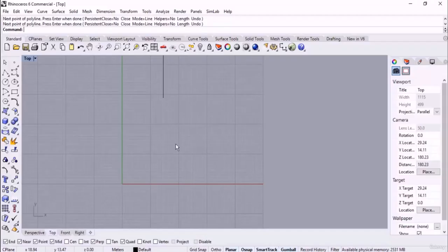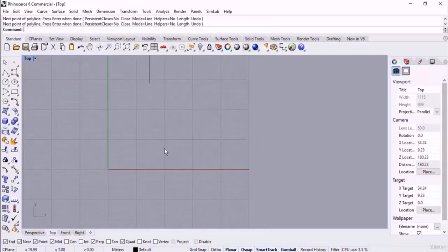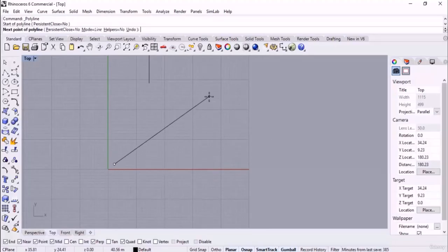Similar to AutoCAD, in Rhino we can use @ sign and relative coordinates. For instance, here I can pick the line, then I sketch it. And suppose that we wanted to move it along the X and Y axis. So what should we do? At first, in the command line, we type @ sign, then we hold down shift. You can hold down shift and then press 2 for @ sign. Then we extend the line along the x-axis, for example 10 units. Then I add a comma and a value along the y-axis, like 15. Check this out. 10, 15 along the x and y-axis.